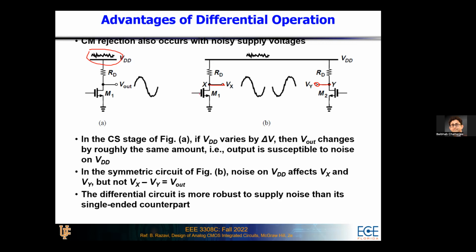If those noises are correlated, yes. So why I said that this noise will go away, because both the circuits, for example, this particular transistor and that particular transistor, both are connected to the same supply line. So whatever noise is present on the supply line comes at the output of both of these common source amplifiers, and because of that, when you take the difference, they go away.